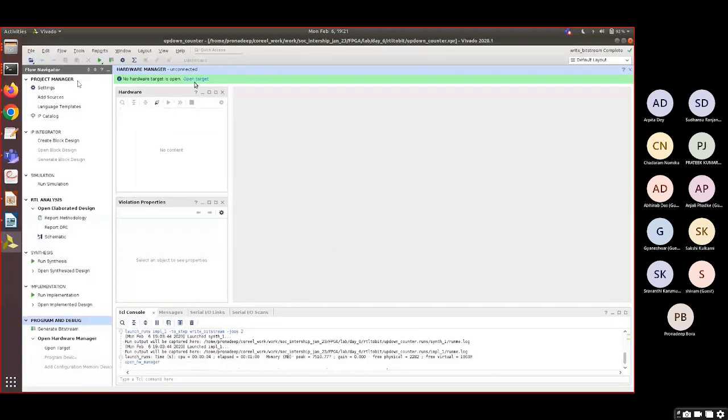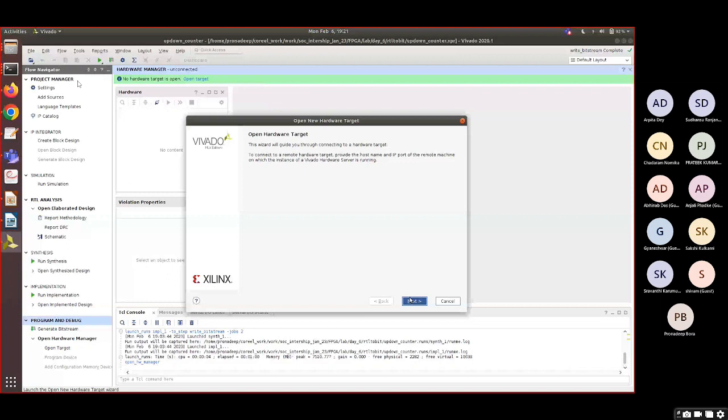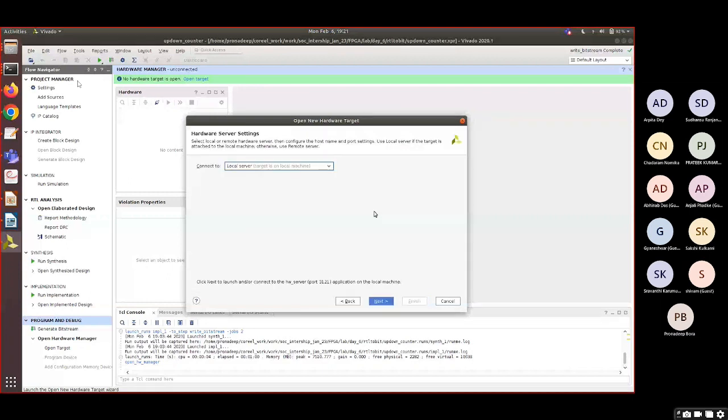Here, I will select remote server. In case Shivam has the Zynq board with him, he doesn't need to connect through VPN or through the remote server. Directly, you can select local server, and only this JTAG pin should be connected. From the JTAG pin, this one will be programmed. There is a J20 pin, program is written here. I am just showing it here again.